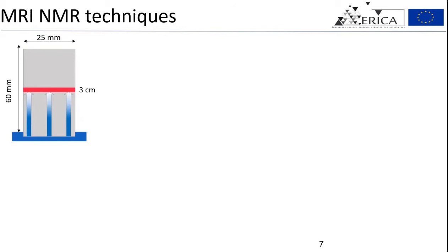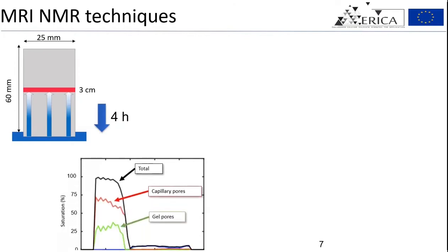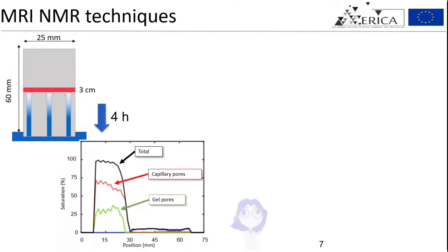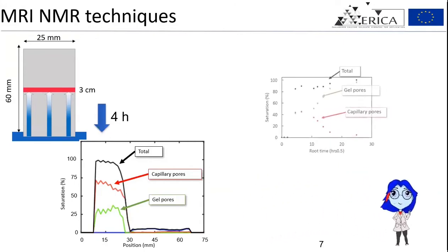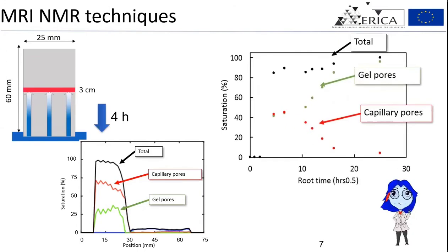The pore distribution across the sample is observed in the image below, where one-dimensional experiments were conducted after 1 hour of water uptake, 3 hours, 1 day, up until 1 month to observe the pore size distribution at the chosen depths. This gives us the plot that we obtain on the right-hand side for filled porosity fractions at sample depths of 3 mm against the square root of experiment time.